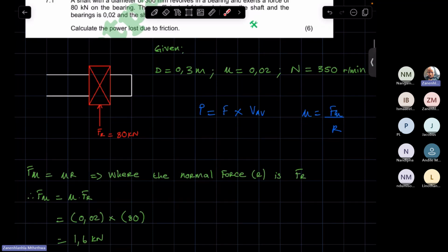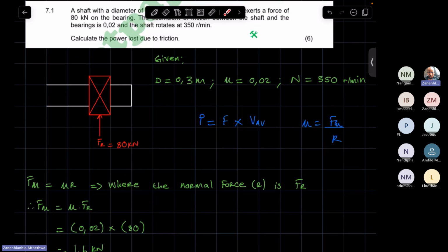He said that since the radial force we know is perpendicular to the line of action, and the normal force, normal meaning 90 degrees, normal meaning perpendicular, it means we can replace this normal force with Fr, which is exactly what you do here. You've been given the coefficient of friction, and the normal force we take as being Fr, because both forces are essentially normal.